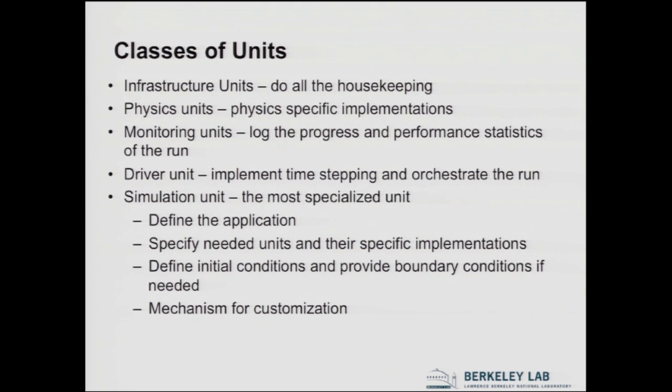Monitoring units are the ones that log the progress of a simulation. So there is a log file unit where, anywhere during the simulation, you can ask for a message to be sent to the log file, and it is just accumulated so that you get it at the end. There are units that collect the performance statistics of the run and summarize them at the end. So after every Flash run, you do get a summary of the performance statistics all through the run.